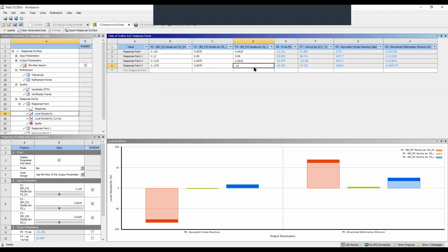I could change the radius. Oh, what's the minimum here? Of course, these are limited to the bounds that we put earlier. So let me try to put 0.08, and let's see if that reduces the stress. I'm going to increase the thickness, 0.068. Okay, hold on. 0.068 was the limit I put here. And let's take a look. Let's make sure we keep our eyes on G5 over here. Yep, stress. It looks like the stress increased, huh? That's interesting. So what if I change the radius?